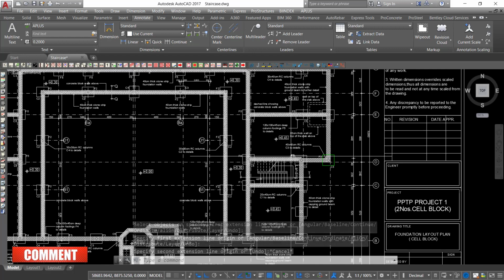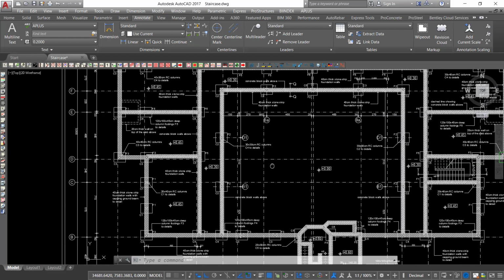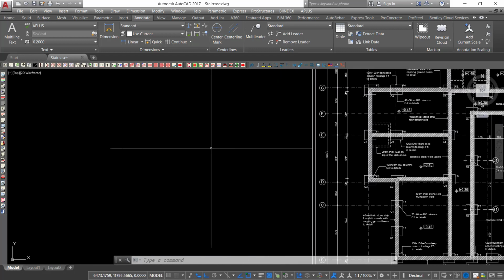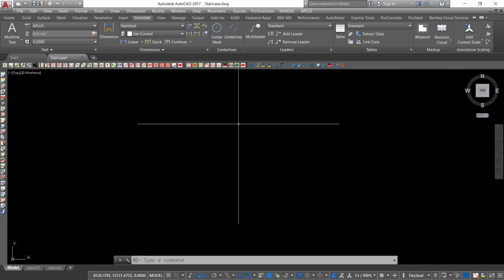Details means we want to extract an elevation view for this and label and give the measurements or instructions of everything that is supposed to be done on site by the contractor or the site engineer. So let me just push this aside and start giving the details right next to this. I'll first of all start laying out the blinding, the size of the blinding, then you come to the column base, then you come to the column itself.